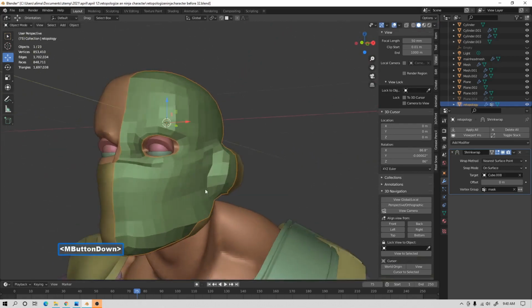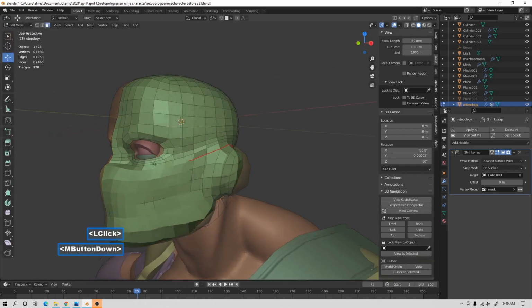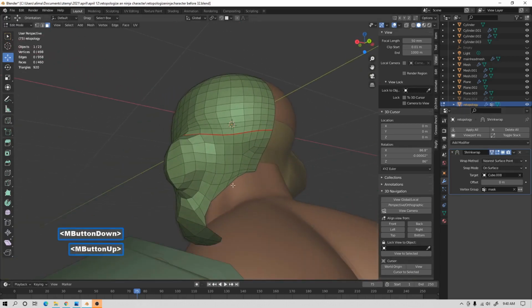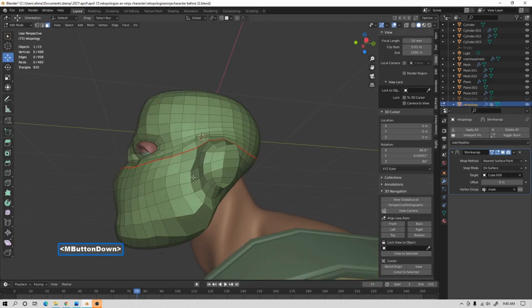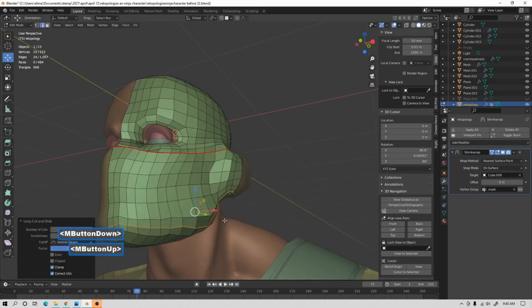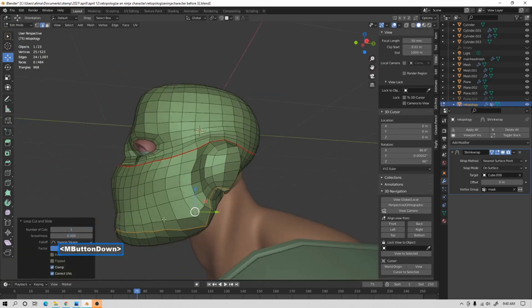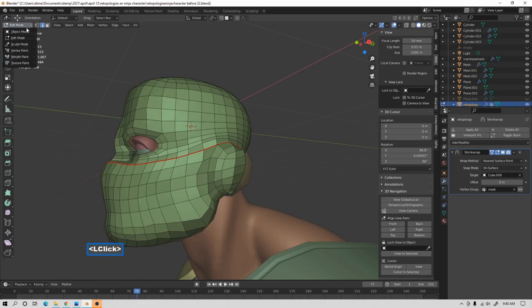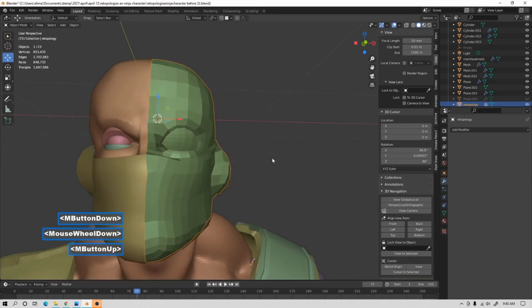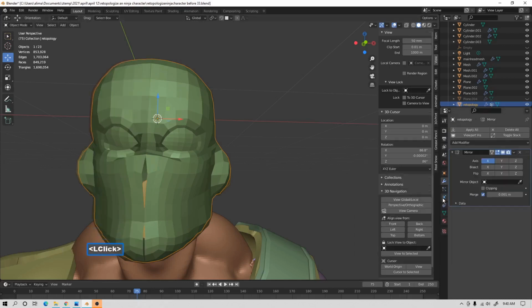the shape. So I'm going to go to upper left here. I'll select here. I'm going to hold Control, press R to put a loop cut here. Back to object mode. I'm going to apply that modifier. Okay, what we're going to do now is we're going to add the mirror modifier back.